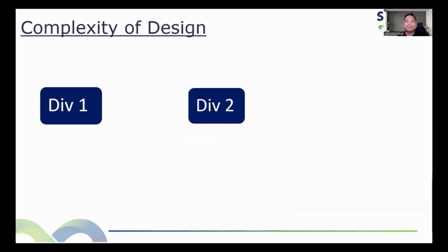When we talk about part 5, you all know that FEA will be there. And if fatigue is there for division 1 also, you'll have to use the same methodology. But if we talk about part 4, design by rule, first forget about the cost, just think about the complexity of design.